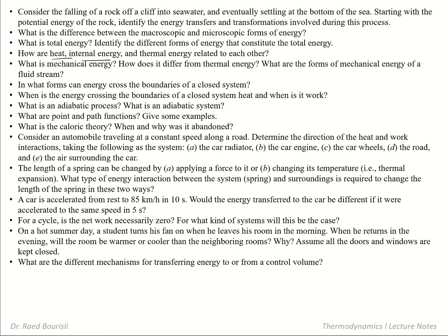How are heat, internal energy, and thermal energy related to each other? Well, this is important. We said that heat and work transfers are boundary phenomena, so they're only recognized as they leave or enter the system. So they're recognized at the boundary. So the system cannot contain heat.